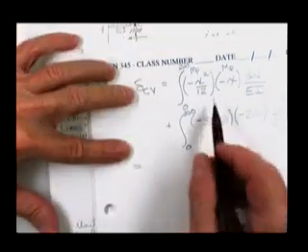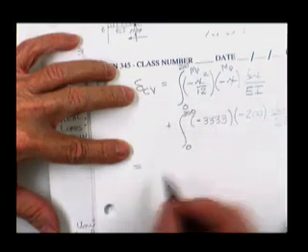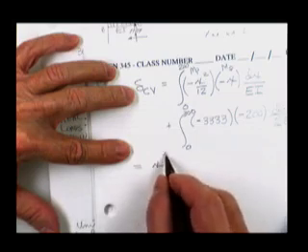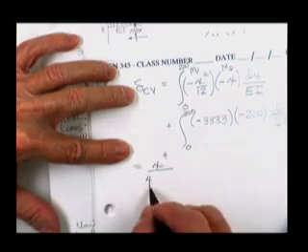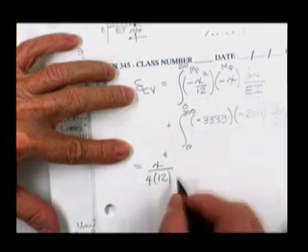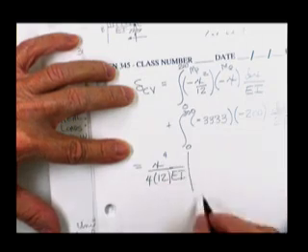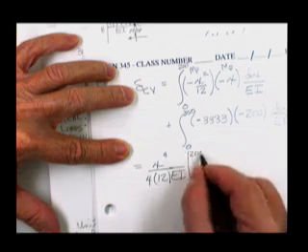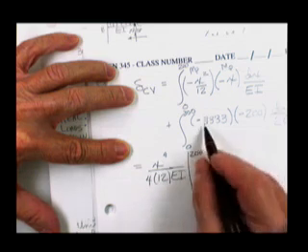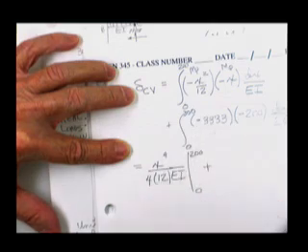All right. The integral of x cubed is x to the 4th over 4. So that's x to the 4th divided by 4, already divided by 12, already divided by EI, supposed to be evaluated between 0 and 200. Plus, minus times minus, this guy will also be an added deflection.